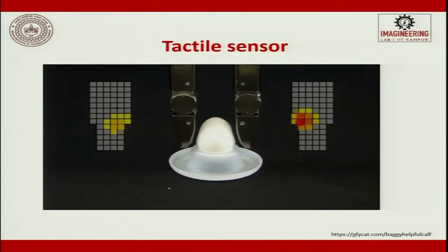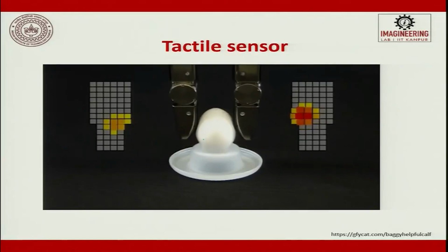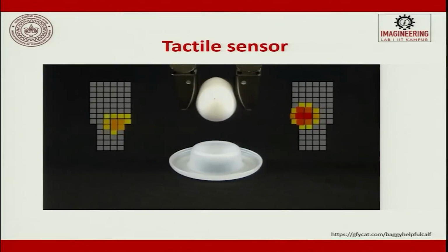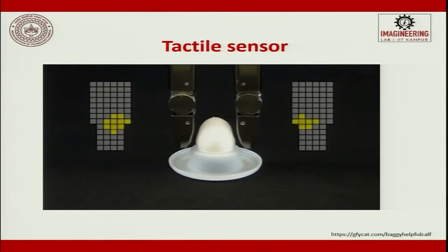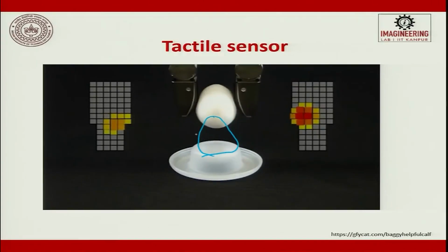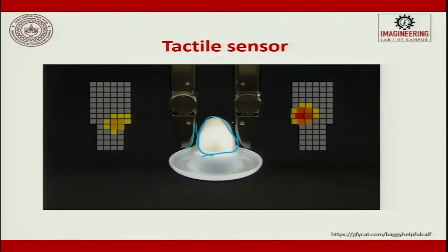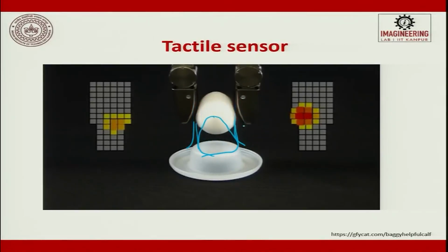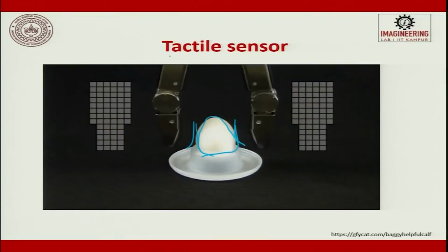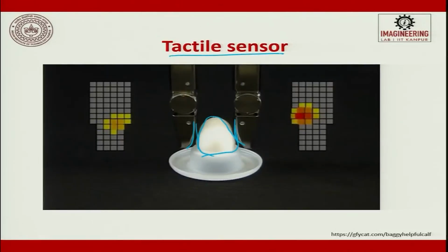So, this is a tactile sensing device. Tactile sensing is needed because lifting an egg is a huge challenge, because an egg is not circular, it is not a sphere. So, it has a shape which keeps changing, and there is a radius, and here if the gripper is flat, you will never get a proper contact. So, what they do is they try to have an inverse of it, so that when it touches, it conforms. When you apply a lot of load, the egg gets shattered. So, tactile sensing is used today. These are tactile sensors which are attached to the end effector.